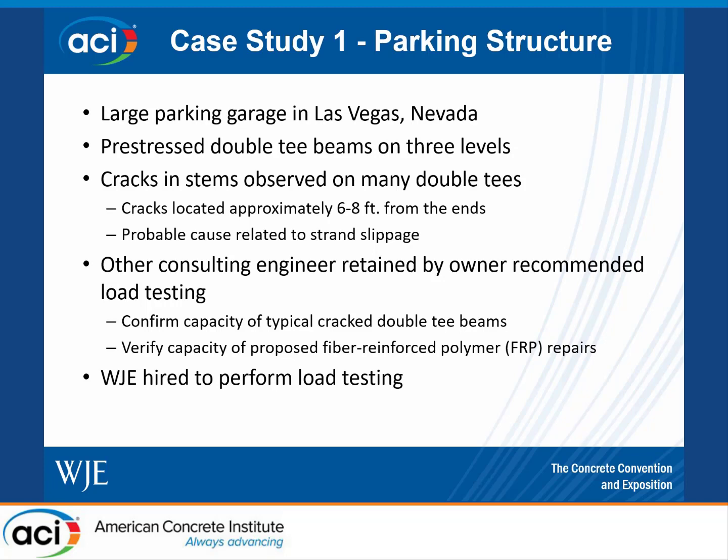So there was a different consulting engineer that was initially retained by the owner who recommended that load testing be performed, and they wanted to confirm the capacity of both the typical cracked double T-beams in their current condition and also the capacity of the double T-beams after they were repaired using a proposed FRP repair method in the load testing.